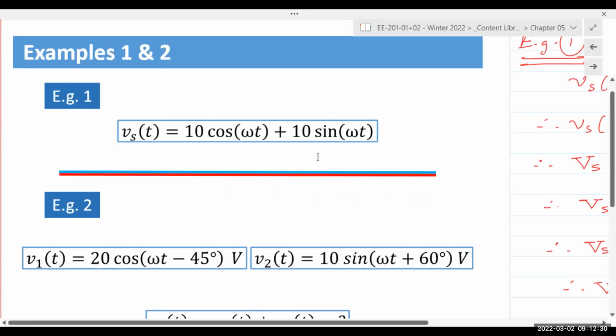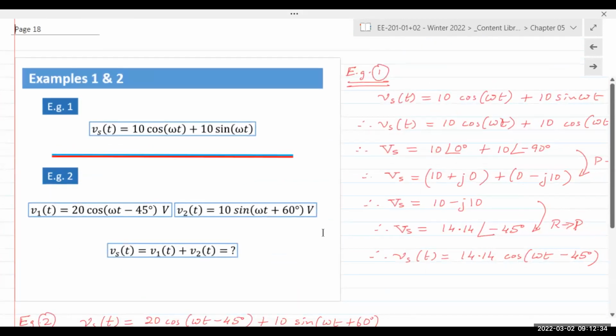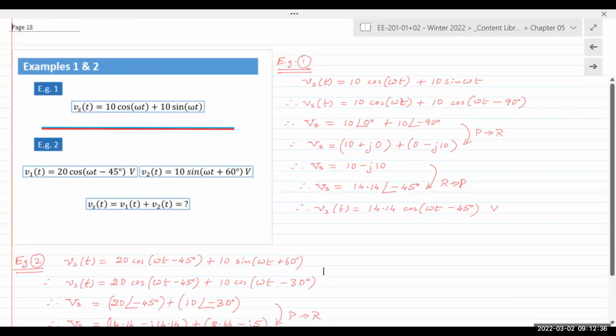So in AC analysis, or more specifically sinusoidal steady state analysis, we saw how we can use complex numbers to solve for currents and voltages when there's an AC source present in the circuit, right? We represent the sources, whether it's a voltage source or a current source, the time varying as a function of time. So we can represent those sources as complex quantities known as phasors.